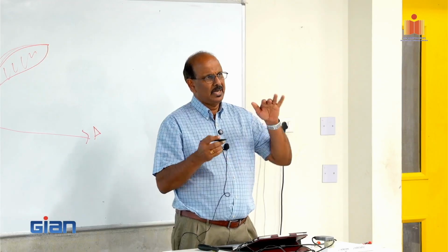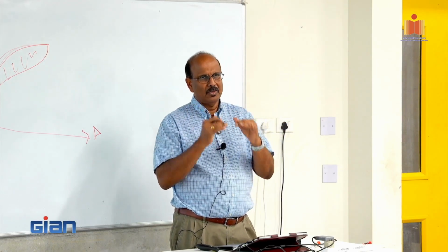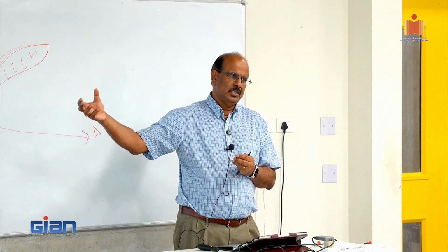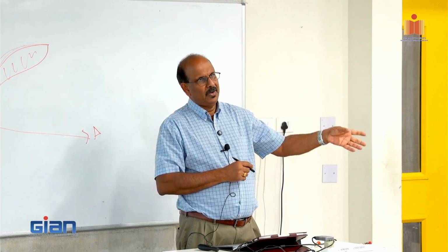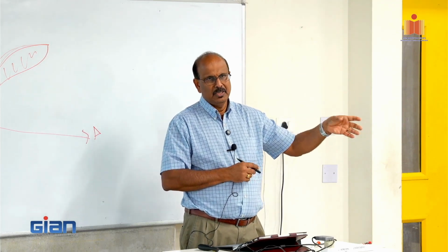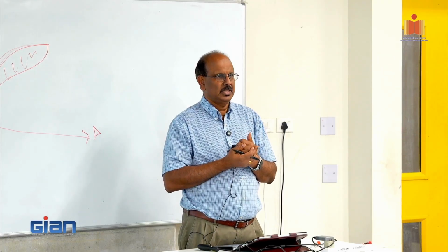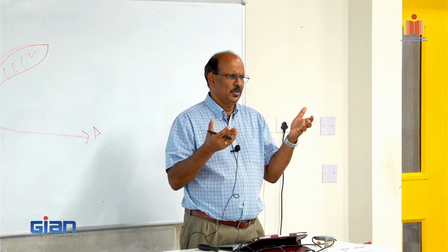So again, I don't want you to go deeper in that space, but even if you're not doing it for seismic, getting exposed to these connections, you need to appreciate that. For example, if you're doing a non-seismic wall connection, you could easily put in an unbonded post-tensioning. You don't need anything else, just put in some shear resistance. You should be good to go.